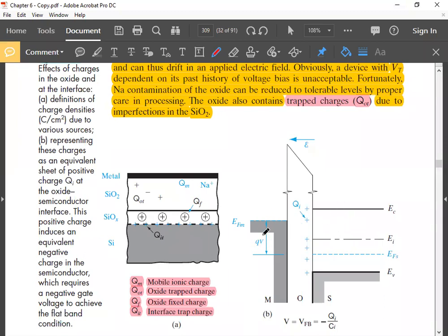This metal layer was not here during the fabrication. Initially, there was a bare silicon layer. On top of the silicon layer, this oxide layer was grown. How? There is a closed reaction chamber, and the environment there is highly pure, meaning very little contaminants are present.